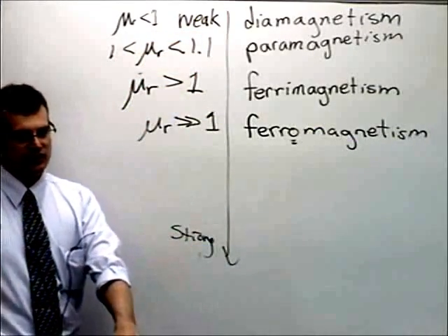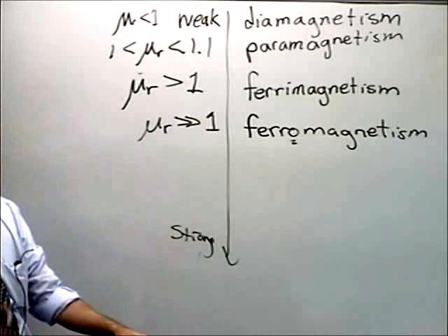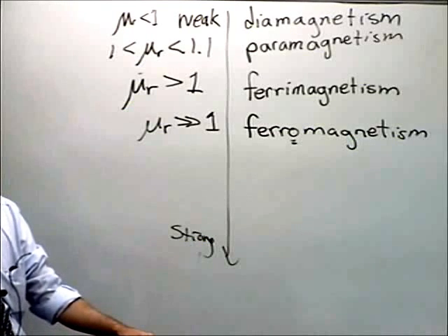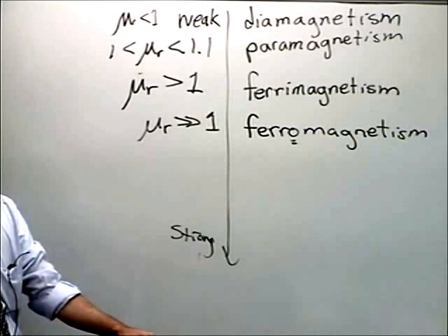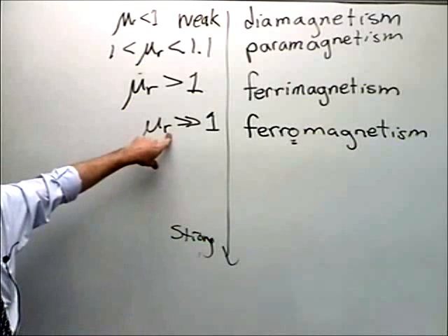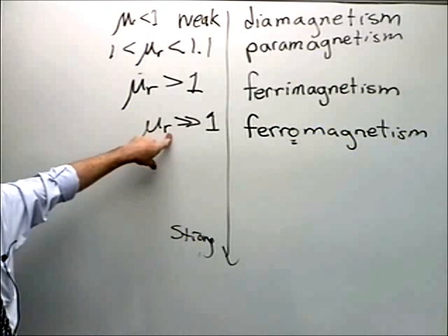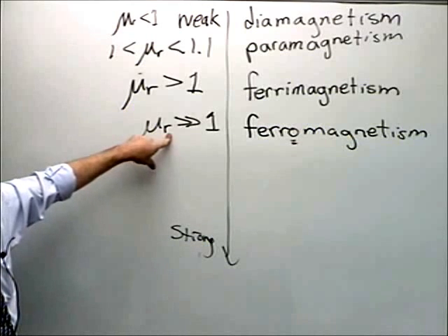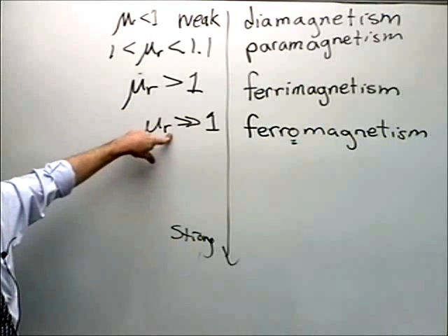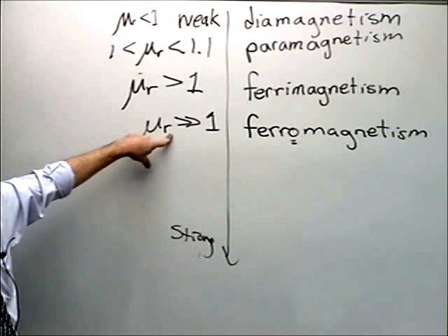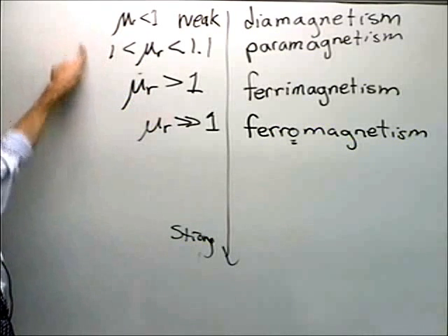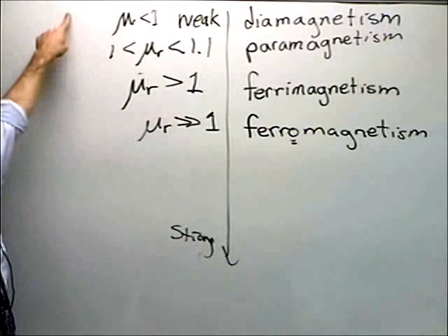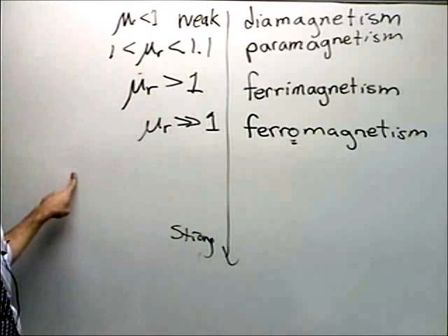However, a lot of times we're interested in alternating current fields, AC fields, oscillating fields. In my field, with radio waves and microwave fields. And here's the fundamental problem with magnetism at those frequencies. The same mechanism that gives you big mu sub r is cooperation, and that's the same mechanism that makes it difficult to change the orientation of the magnetic field. And so what you will find is that there is a corresponding frequency limitation for each of these that goes down with respect to frequency.